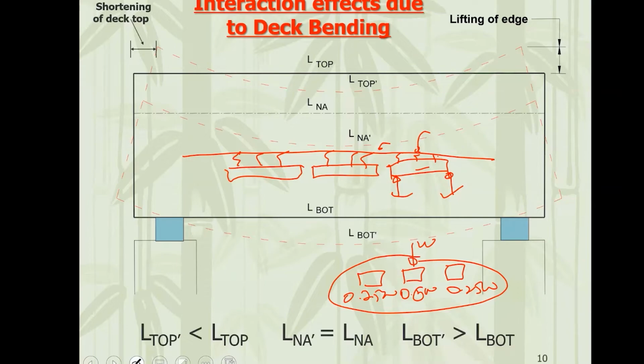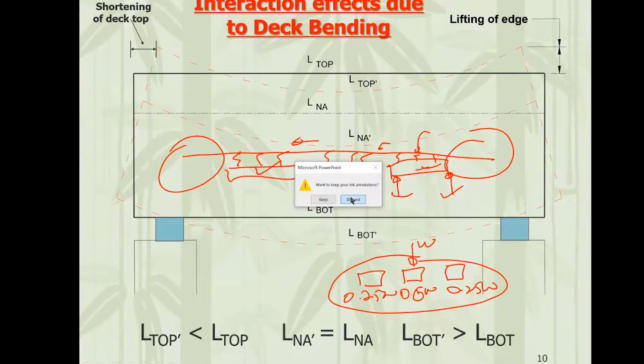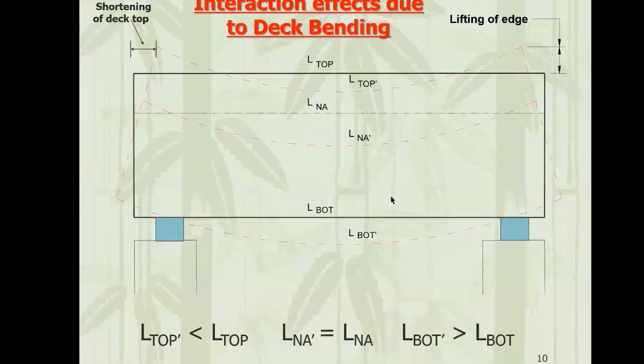But when there is a longitudinal force, because in the track we also have the longitudinal force coming from the train, tractive effort or braking force, how much of that longitudinal force will go to this span and how much will go to the next span or approaches cannot be determined by simple static analysis. It becomes an indeterminate problem, of sort of infinite degrees, so it cannot be solved manually. You have to go for a computerized solution.